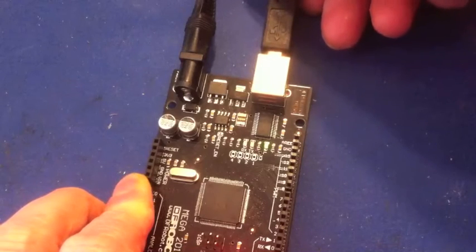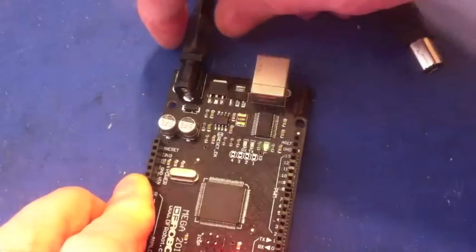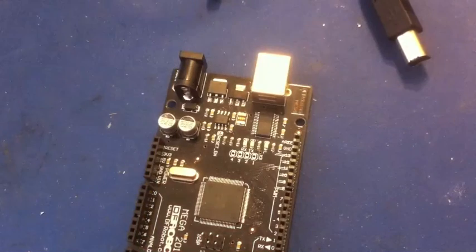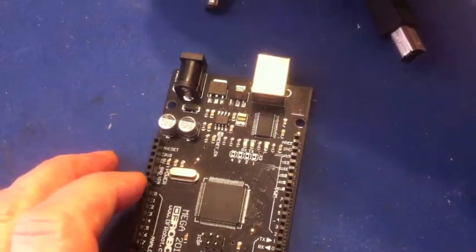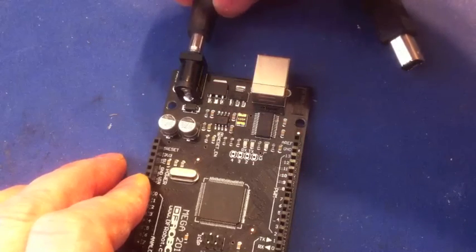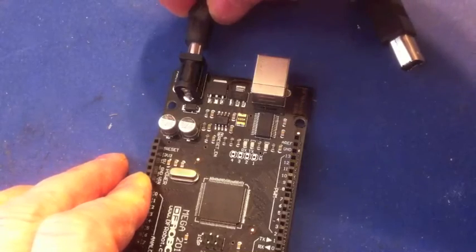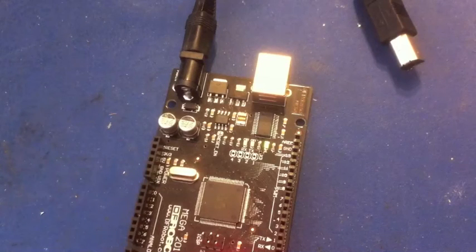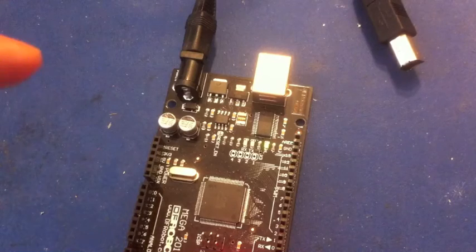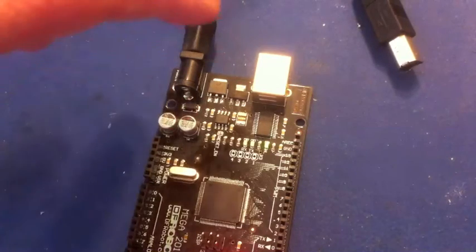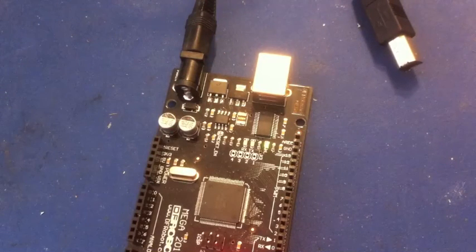So for the same reason, we can pull this out, and if we pull the power now, obviously everything will switch off. But what makes it useful is when we put the power back onto the board, it will activate the last program that we compiled over to it. So it will remember that program and always run it every time we plug this in, unless we overwrite it with a new program. So there you go, you see it's almost instantly back on. So that's good. It means once we've developed our projects, then we can burn our program to this board and use the board in the project in any way we want.